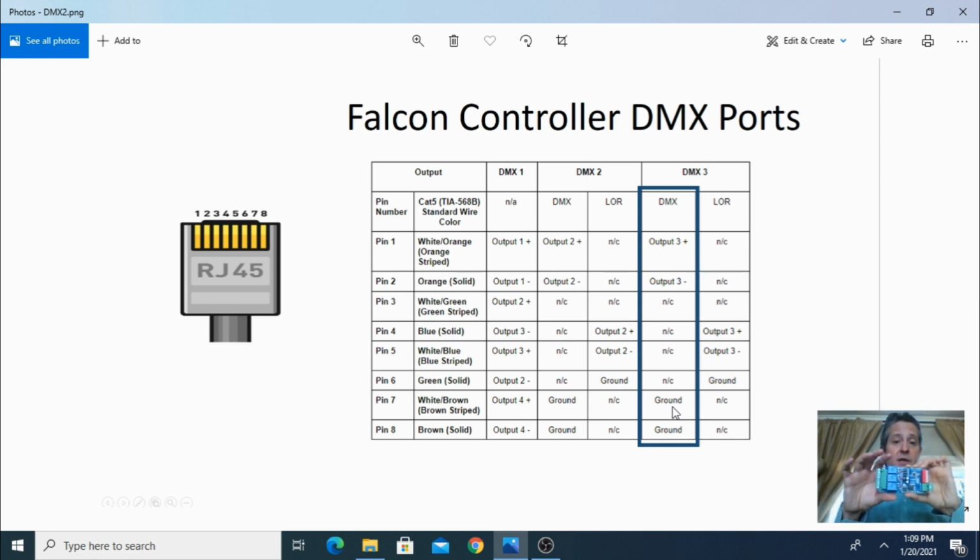This is rated for DC and AC alternating current, so up to 250 watts, 10 amps. So keep in mind that 10 amps is as much as you can run. So we're going to use 125 volts to run these lights because we just plug them into the wall.